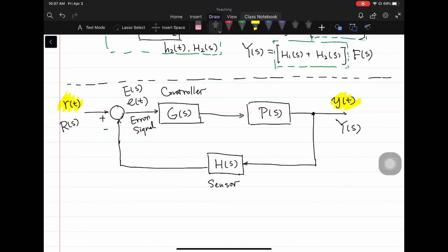Which calculates and actuates the control actions. For instance, how fast you want to blow cold air out, right? Or how much power you want to apply to the heating coil. Then the controller and the actuator, which sometimes implement the control actions, will blow the air into the room, and the system you're controlling is called the plant.